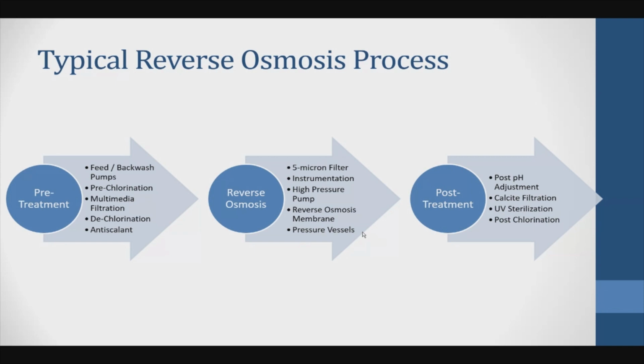There's another way: if you want to increase the pH and neutralize it using no chemicals, it's a good idea to use the calcite filter, where it neutralizes and raises the pH a little bit, so it becomes very close to a pH of 7. Now, if the reverse osmosis water is going to be used without storing, or if the storage tank is for a couple of hours, it wouldn't be a bad idea to use a UV sterilizer after the reverse osmosis, so in case there's any virus or bacteria in the piping, the UV would take care of it.